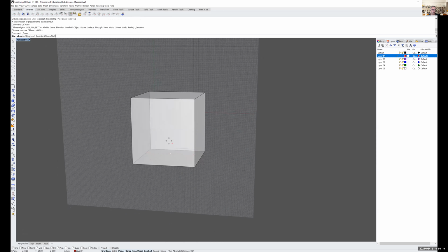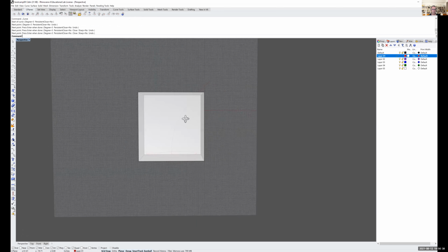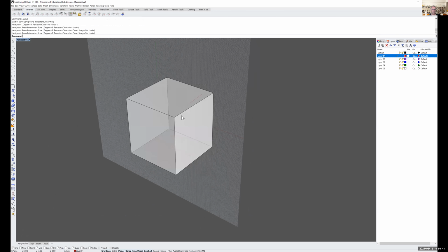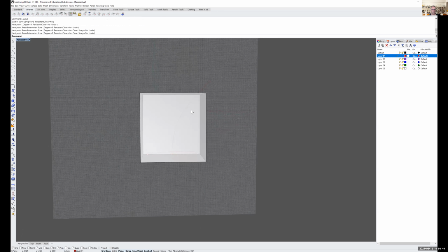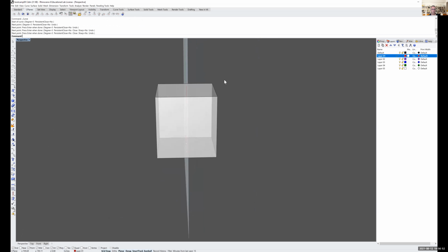And all of this, I'm trying to be a little more specific for some of these things, and maybe it's too much. We could be a little more sketchy with it too. Basically, what I'm trying to do is draw a line that starts at the bottom and comes out the side. I want to use that line to put a couple more shapes on, so that we can loft 3 shapes together. I was going to do it in the front view, and then also do one on the side view, so that we'll have 2 intersecting shapes. We'll get 2 skylights from that interior volume.